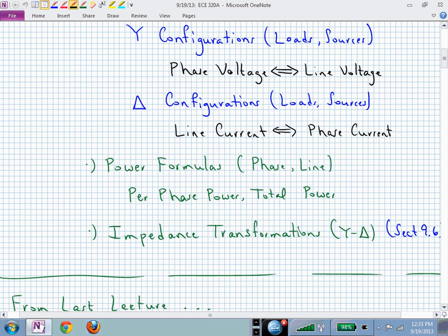In a real quick nutshell, if you have balanced loads, then you can quickly use a factor of 3 to convert between delta and Y-connected loads. So this factor of 3 translates those for you rather quickly when you have a balanced configuration. If you think of that, it's kind of small, but the Y is inside the delta. The Y is the smaller quantity.